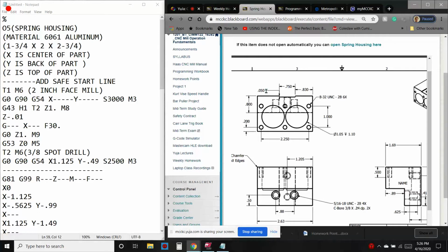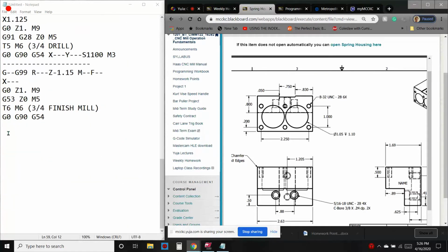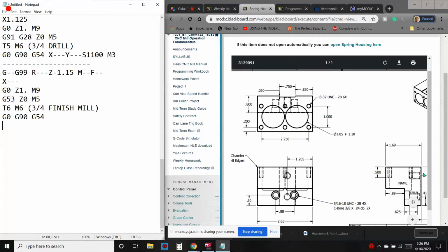So if you made this exactly Y0, that would end up being raw material. But I think we'll just program it to be Y0, and then if you actually did set it up, that would be up to the setup person to move that Y minus 20 or 30 thousandths so that would actually be a cleaned up finish if you wanted that. There's plenty of material for it to be cleared up all the way around. So, all right.